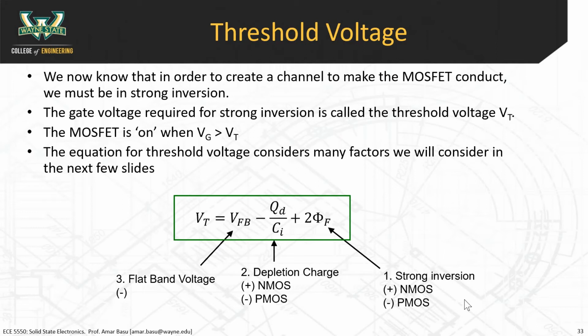If you're going to make digital logic gates or you're going to make analog circuits, you want to make sure that the threshold voltages across all the transistors on your wafer are relatively uniform. Okay, so we're going to touch on ways of controlling threshold voltages, but let's remind ourselves what the equations are. A threshold voltage for a standard MOSFET device that we've talked about in this class has three components to it.